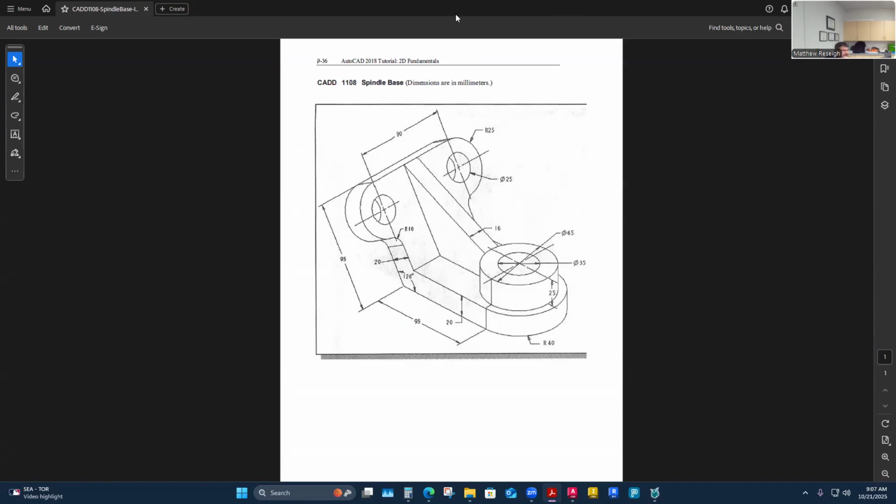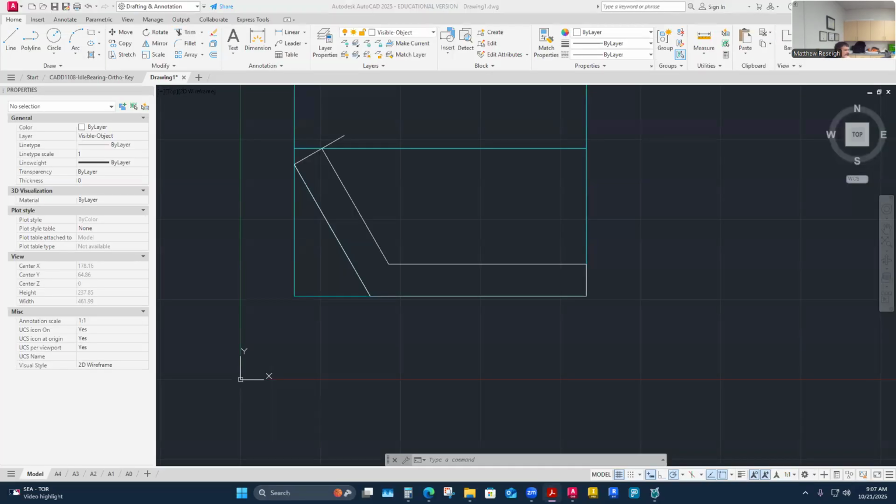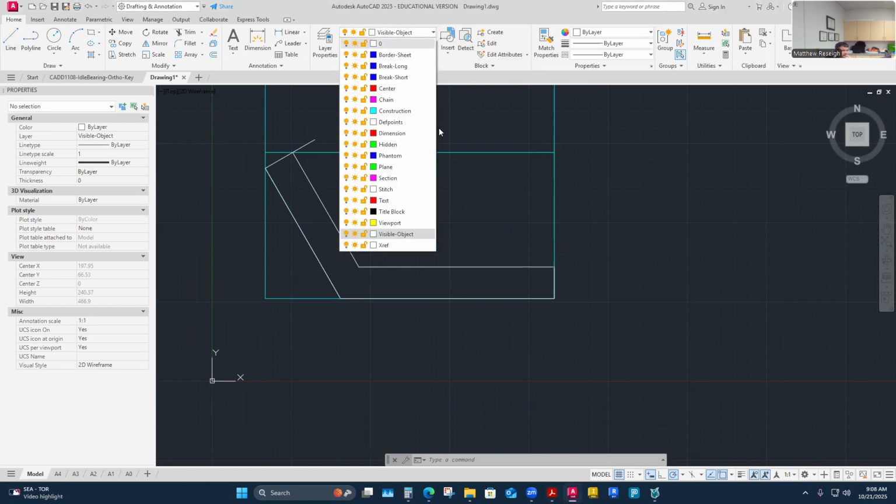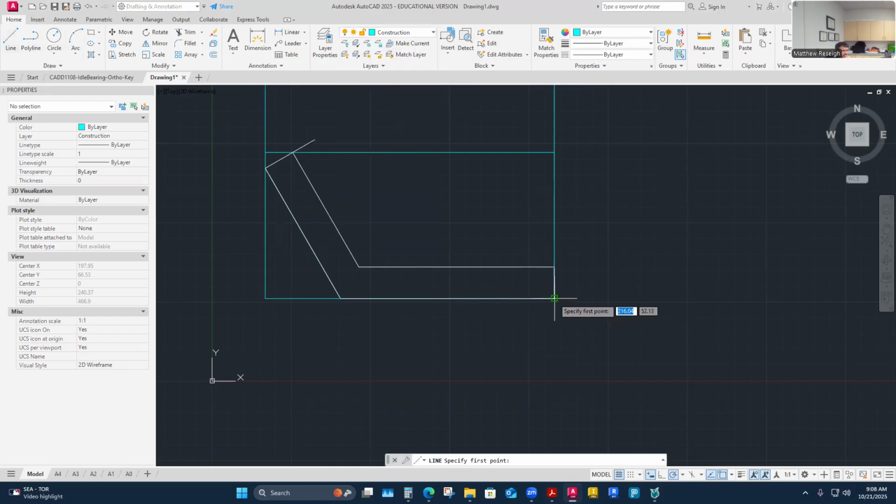Okay, so I'll have that up to detail that. Detail those cylindrical features in their rectangular view here. So what I want to know is, maybe I just need to know where the center of that is. So I might just cursor over from here like 40 millimeters. That's the axial center line that they all share. So maybe I'll just pull that up through my boundary here. So all of those are based off this. This is essentially a center line. And this is a foreshortened radius surface that I'm looking at here and a nice flat surface that I'm looking at here. This is the point of transition.